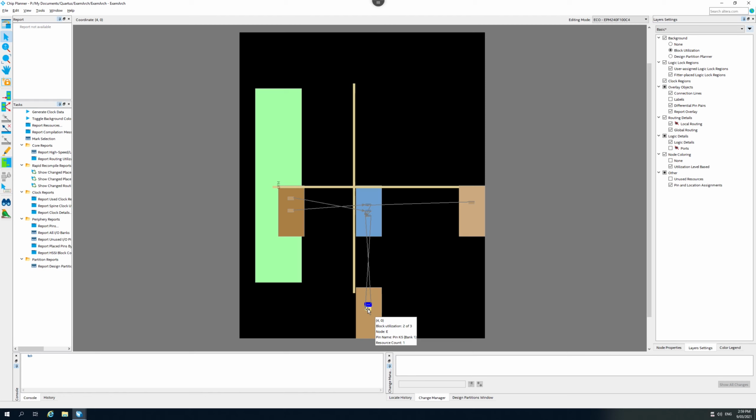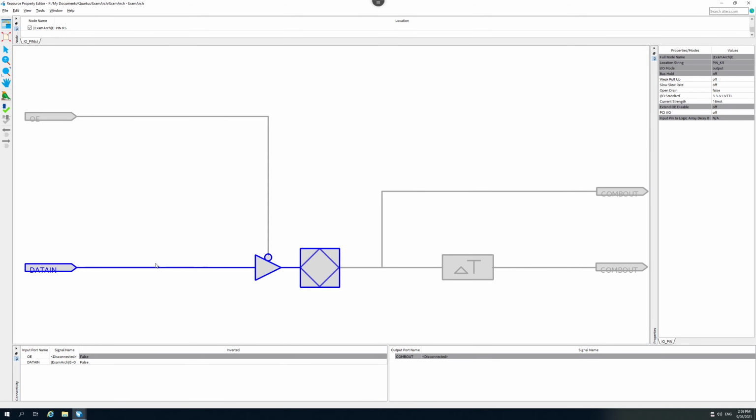This particular one is an output, and we see that because it's an output, we're now not using the part on the right, we're using the part on the left. So remember, these pins are highly configurable. Each pin can be either an input or an output. That's part of the configuration. So this pin is being used in output mode, and we see that the signal is going to be sent out of the board.